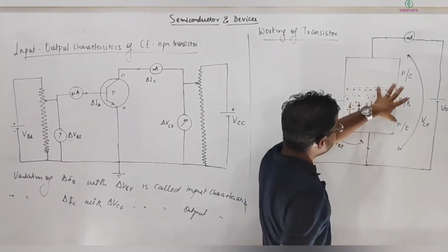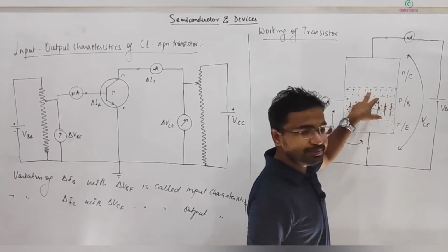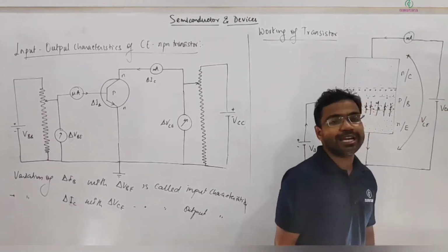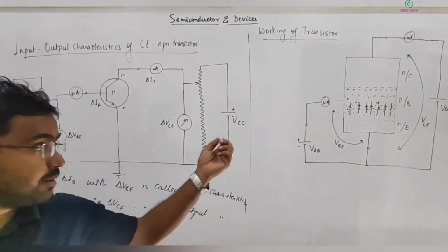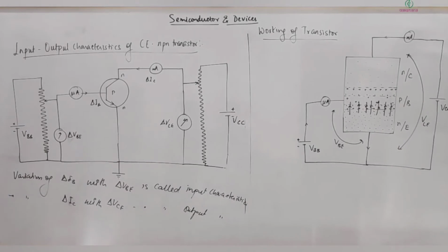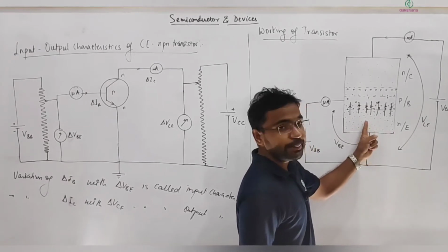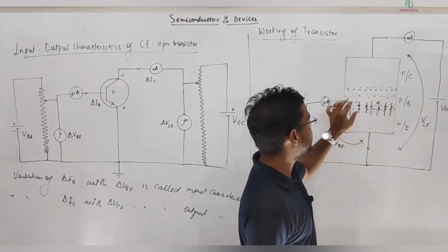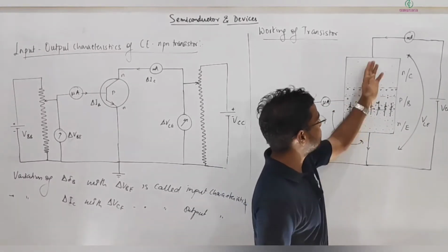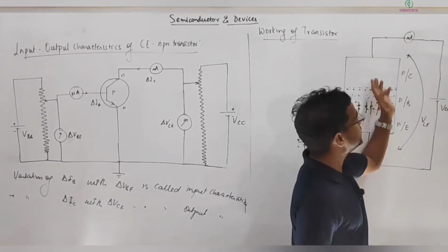The remaining electrons will also feel some force or resistance due to this battery, but they will feel some attraction, and to pull them to that side we use another battery towards the collector side, which helps to pull these electrons. So the remaining electrons, which are most of them, pass to the collector. As electrons move from emitter towards collector, only a few combine with the holes, which is a very small current in the base, and the remaining electrons are pulled by this battery towards the collector.